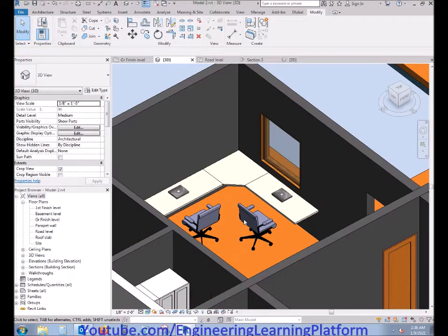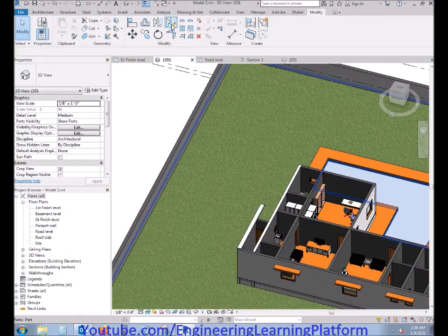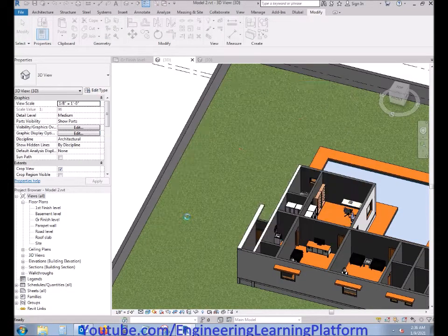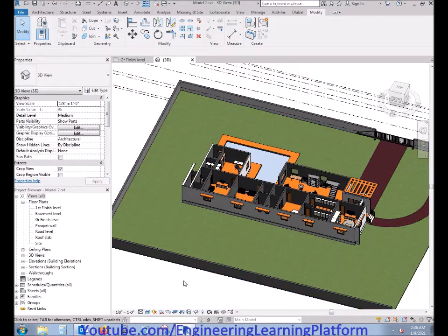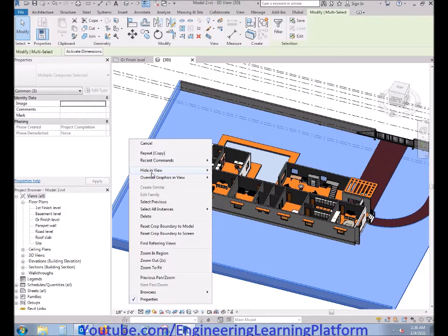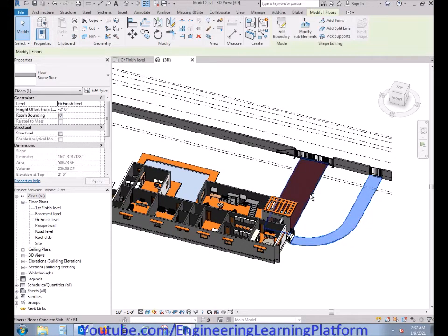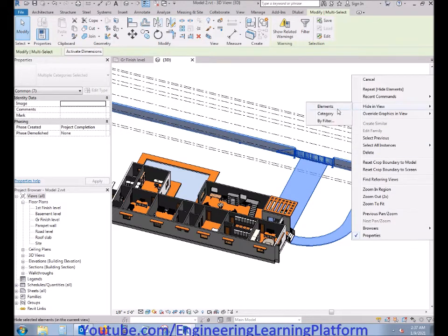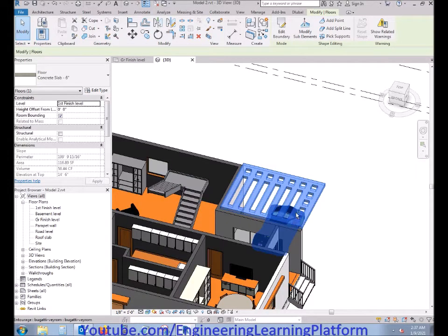In order to speed up the modeling, you can switch the realistic view to shaded view if you have a low configuration graphics card or other system limitations, which you can see on the Autodesk website. So now I'll be turning off visibility of the objects that are making my model heavy. The elements are there, but I have just made them hidden for the time being.